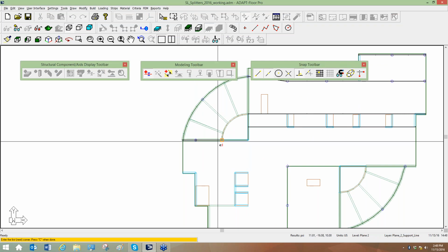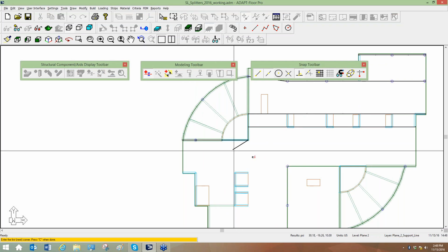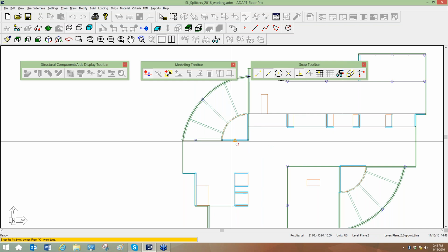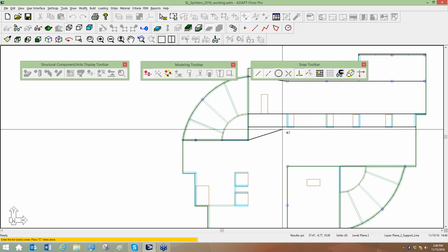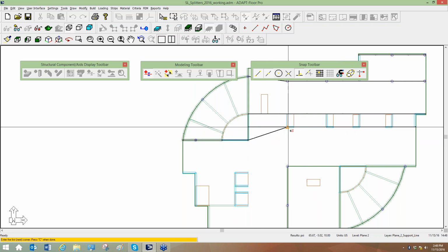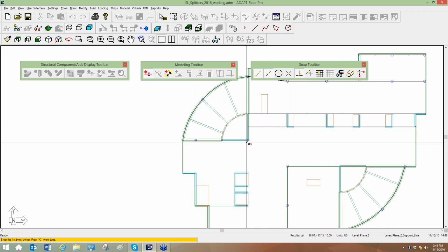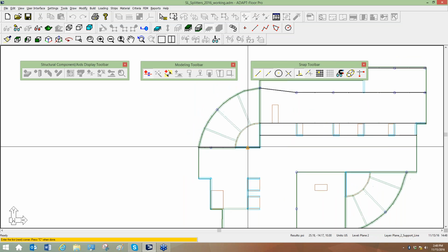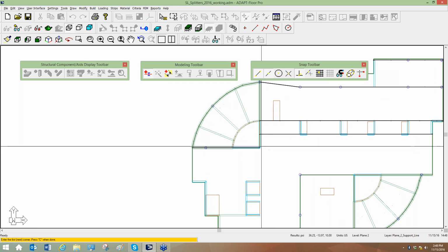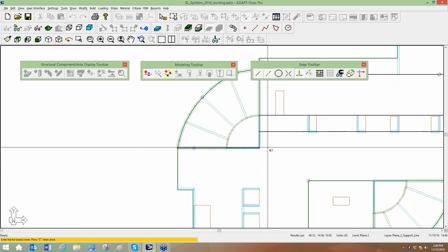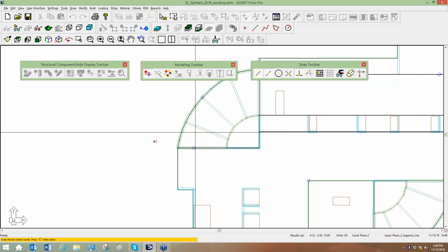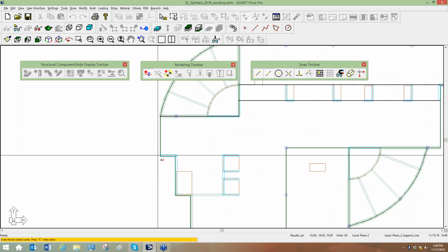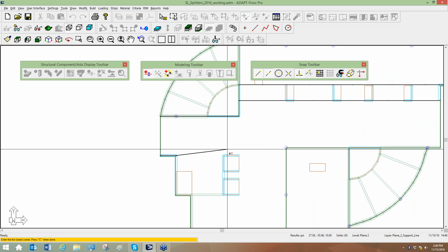I'll go ahead and hopefully get more of this done. This is a condition where we're going to terminate the support line at the corner. It could go to here. I mean, that's a viable load path, let's say, from here up to there, but we're going to just stop it. We'll assume this being the banded tendon direction, we might anchor a tendon out here and then run it through and exit it out on the right or the left-hand side. So that follows, for example, my tendon path.